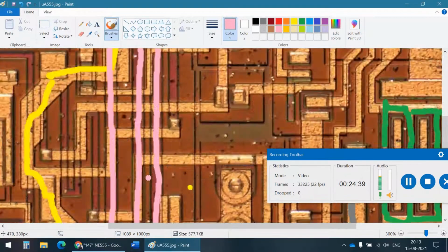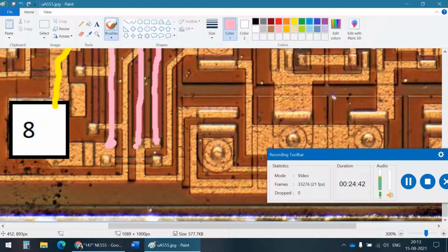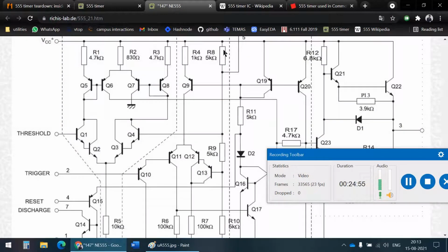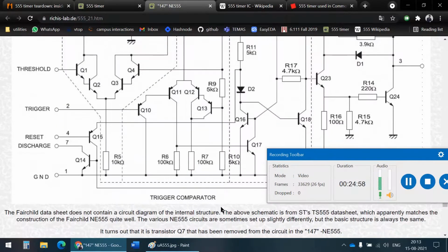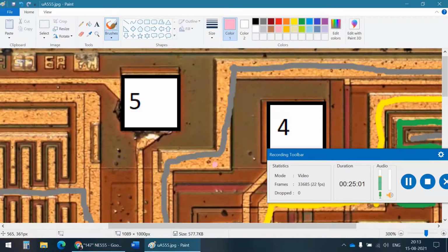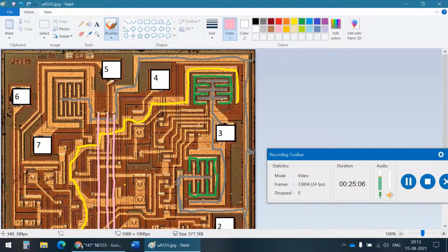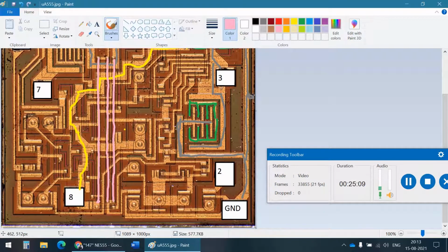now the end of this resistor is not connected to the first one. So we know that it's not in parallel, it must be in series, and it's connected to the third resistor, which seems to be connected up here, which is connected to this brown thing, which was ground. Is that right? So that's 1, that's 2, that's 3, and the third one is connected to ground. So we're right, we've identified the three big resistors, the three 5 kilo ohm resistors here, and we identify that it is in series with one end connected to VCC and one end connected to ground.